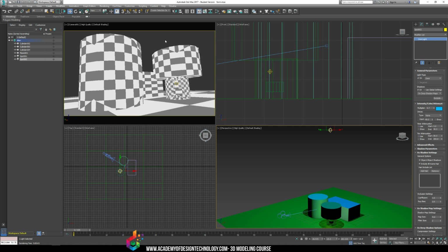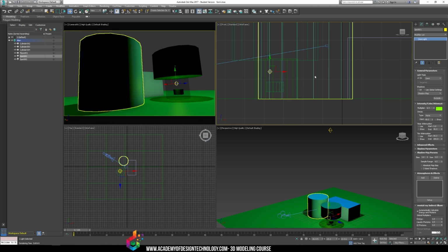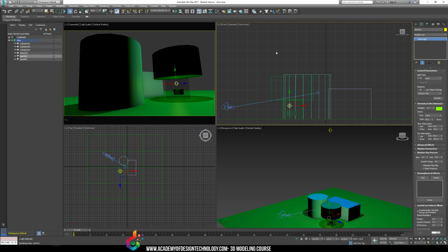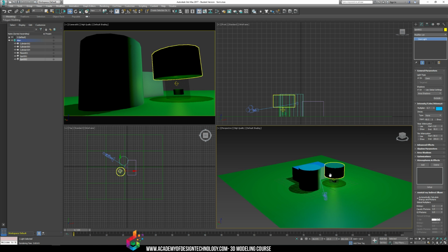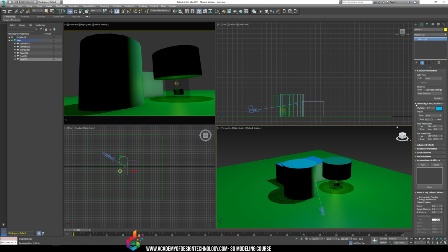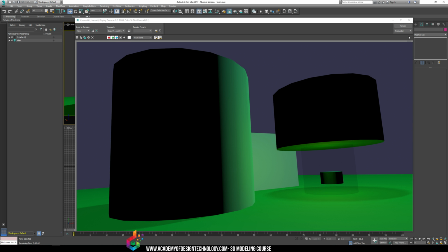But the one important thing I always find in shadows, as you start playing around with them a lot, is that you're going to want to have a difference in intensity of the shadows. Shadows are never really fully black because normally they're lit by something else. So when something is creating shadows, like this in our scene right here, and I'm going to put it back to area shadows, normally the shadow intensity is going to be lower. So if I look at intensity, color, this kind of stuff, we can change the type of decay our regular light has, how far that light can go. We can change the advanced effects if it's ambient only, if there needs to be a projection map, meaning it's only shadowed or lit in a certain way. We can actually change the shadow parameters too, which changes the density and the color of the shadow. So if I want to, I can change the density of the shadow to, let's say, 0.5. And then I know that the shadows are actually a lot lighter. You can see these shadows are actually a lot lighter here.